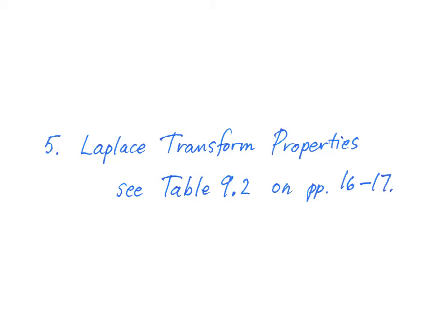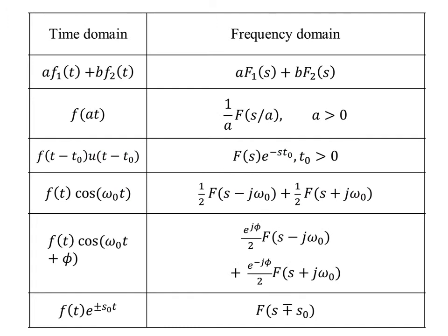And let's take a look at the Laplace transform properties as well. These are actually more interesting because now we've gotten used to working with transforms. We know that the properties are very important. For example, the first one, linearity. This is absolutely a must if we are to handle signals adding together before they are applied to a system. So the additive property as well as the superposition property are very important at allowing us to analyze linear systems.